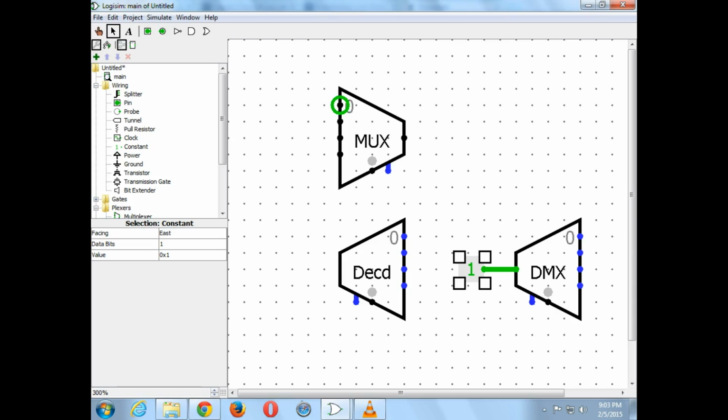You still have the same control mechanism, which is the enable. In other words, if enable is a 0, then all of the outputs are not driven, they're all floating. So you still have the critical clutch to disengage the input from all of the outputs. So all the outputs will remain floating. Then somebody else can be either driving the line or no one is driving the line.